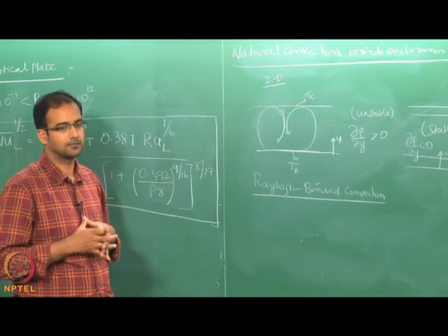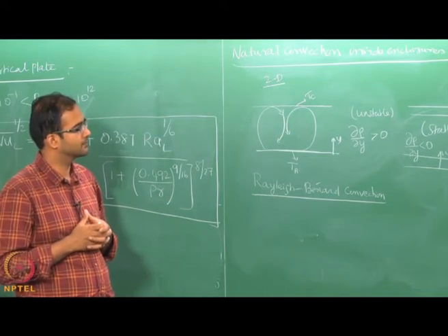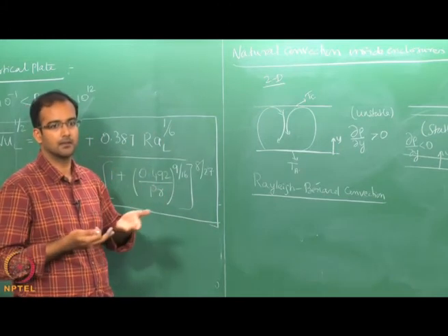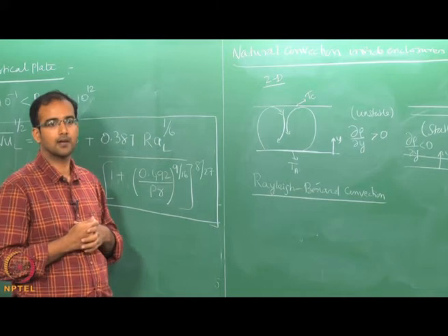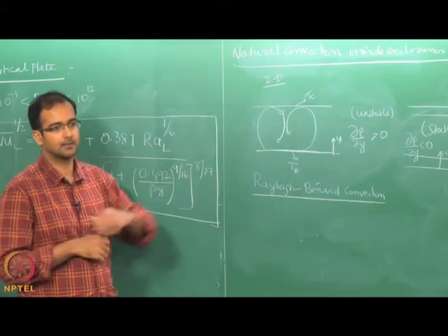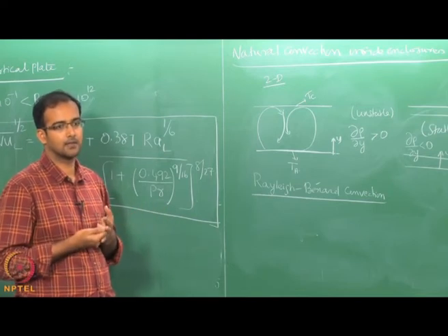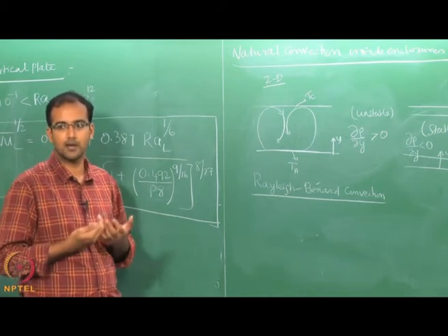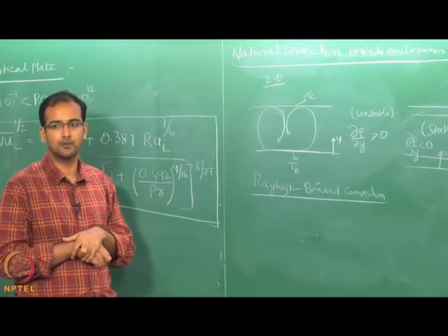So, in this case also the inverse of it should happen, right? That is from TH to TC there must be, but TH, the lighter fluid can only rise up, it cannot go down. So, therefore, you cannot have a convection from the hot to the cold in that case. So, this is always buoyancy aided convection. You cannot have a convection which is opposing the buoyancy; only the buoyancy has to aid it. So, the natural direction for buoyancy to aid is d rho by dy greater than 0, right.